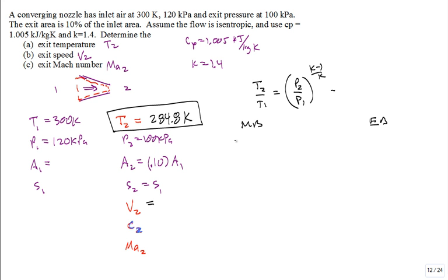What's the mass balance? It says m dot in is equal to m dot exit. Well, how do I calculate the mass flow rate? Isn't it rho density inlet, area inlet, velocity inlet equal to rho exit, area exit, velocity exit? So, the density of air, is that going to be pressure divided by RT1?